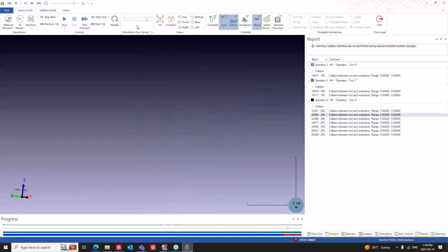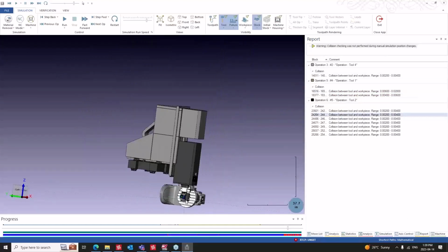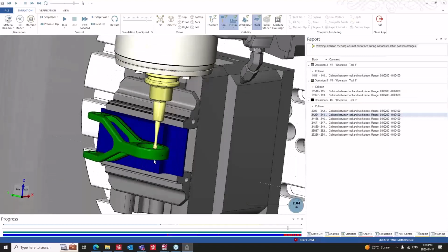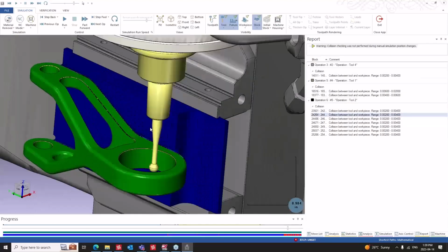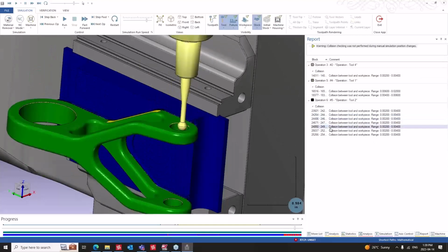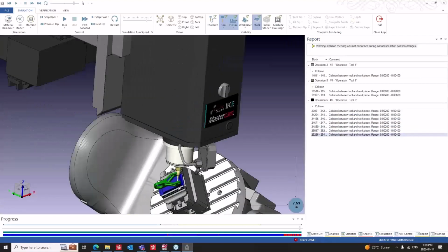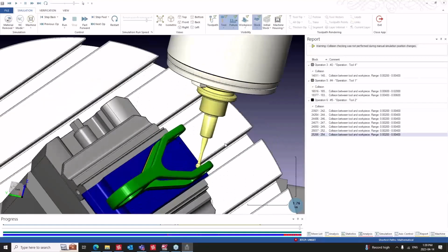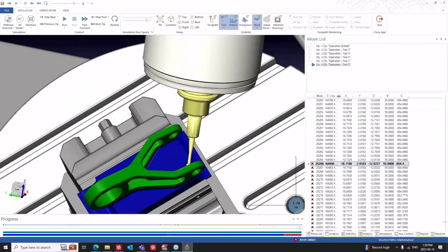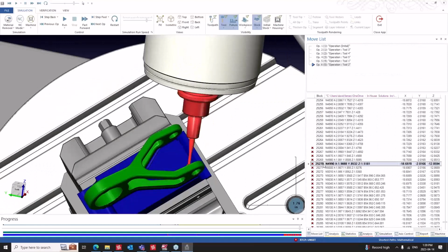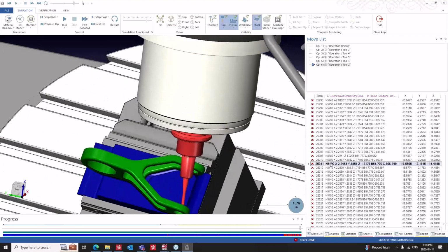I wanted to show you this one because this is how accurate this thing is. It's stopping on these chamfers around the outside, because we've programmed in a chamfer all the way around here, but if you look at the actual model, there is no chamfer. So it's stopping on those chamfers and catching every one of them. It even catches chamfers, right? And again, you can go back to the CNC code at any time and you can forward this and you can see the actual movements.